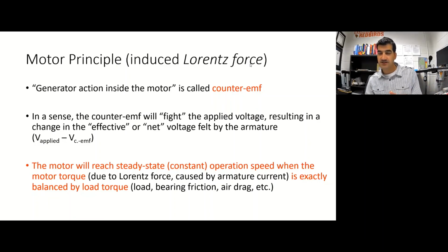Here's a little clarification. The counter EMF is never going to exceed the applied voltage, but they will be very close when they're at steady state, which means the motor is neither accelerating nor decelerating.